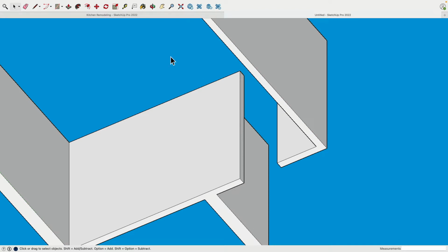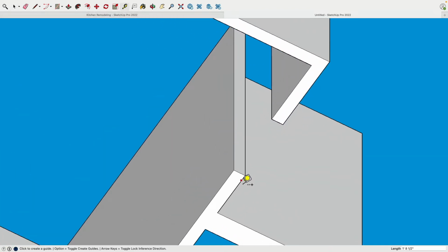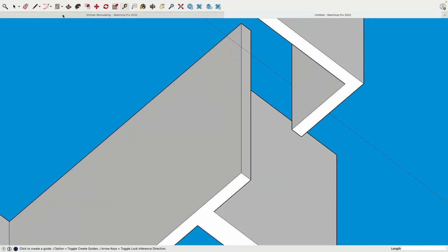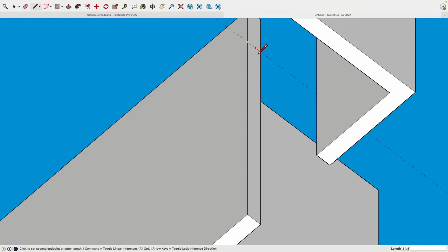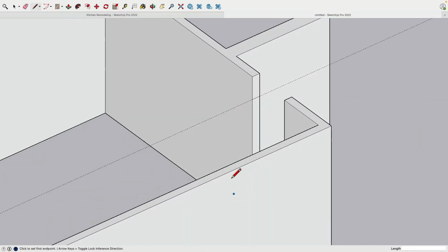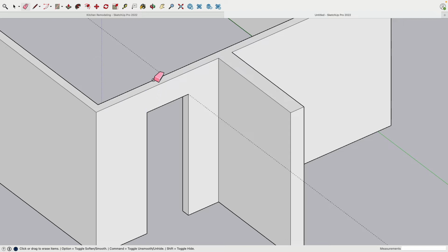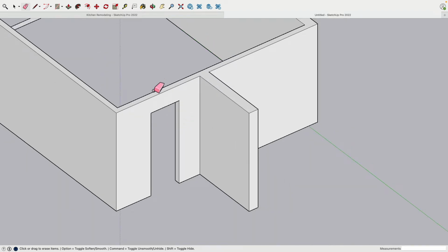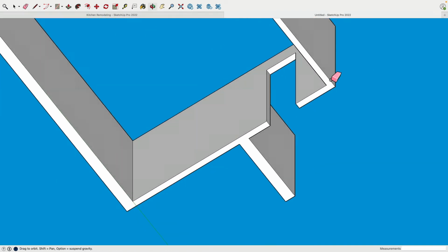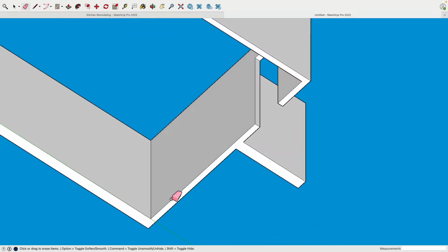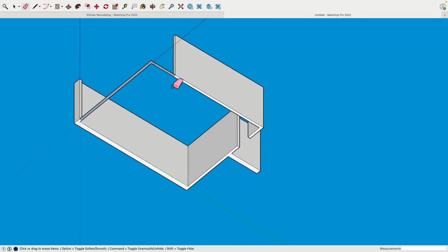From the bottom up, that's actually 80 inches for the height. So I can add a guideline, 80 inches. There we are. And then there I draw a cross line. You see? Very good. And then this we connect. Oh, look at that. SketchUp fused it together. There I removed these other lines. And there we are.